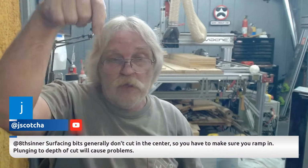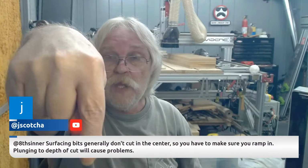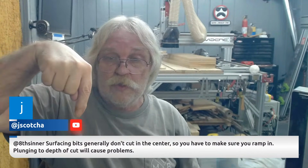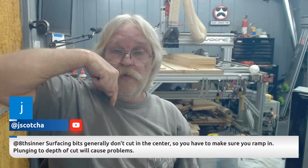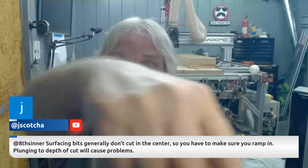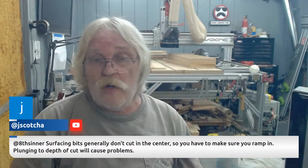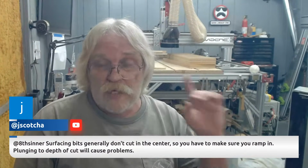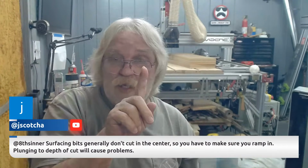I know the plunge is going to be done off the material. It's going to then come across the material and do its surface, off the material, then move over, then come back and do like so, then move over. Been doing that since day one, and I've yet to burn a piece. I've yet to have machining marks where you can see that scoot over.